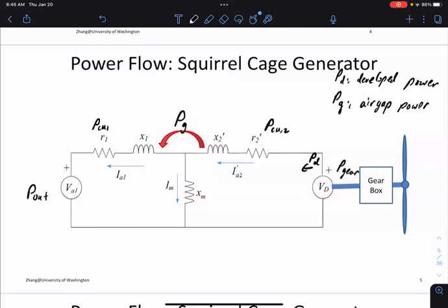About IM, do we normally consider it or do we ignore it most of the time? So IM in power calculations, right? The shunt inductor, in active power calculations, it doesn't matter. There's no power loss in that branch anyways. What IM does is make your current calculation a bit more complicated. So normally we do not consider IM.